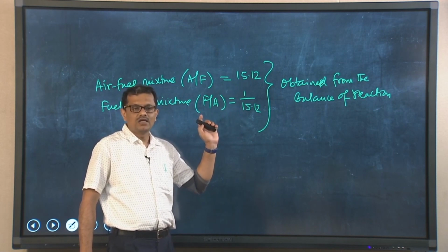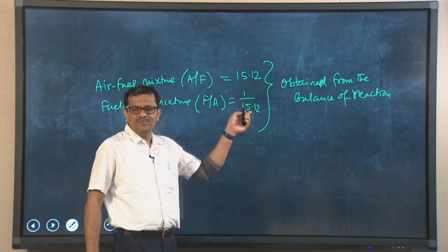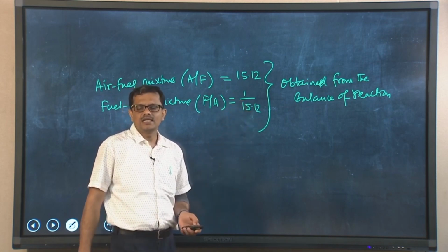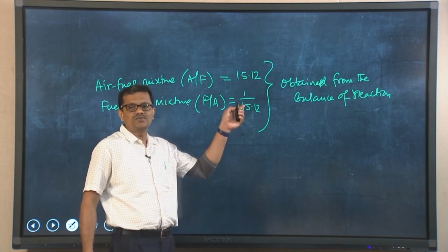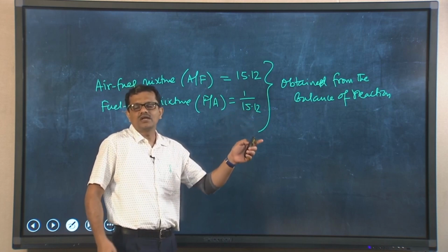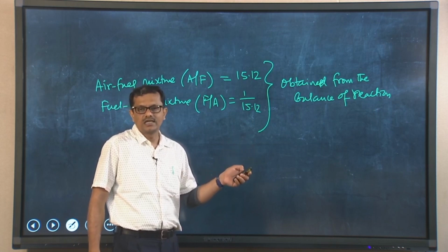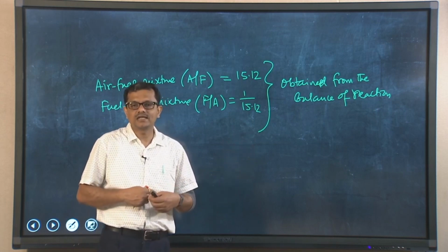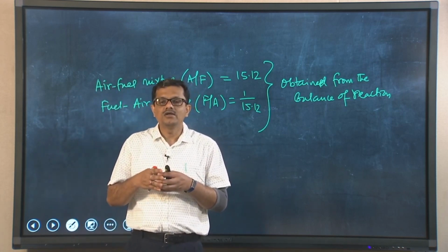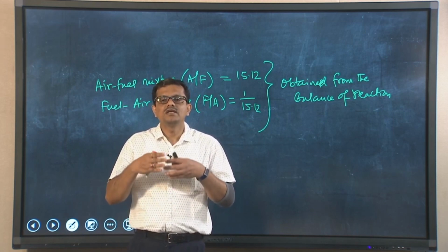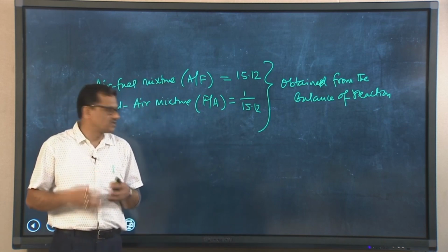If we need to run at this condition, the carburetor would need to supply this ratio, but it is very unlikely that any mechanical element or component will be able to supply this ratio for a long time, and it is also not needed that the engine always needs the stoichiometric air fuel ratio. Instead, there must be a specific range for which the engine would be able to run efficiently following proper combustion, and that specific range is known as the combustible range.